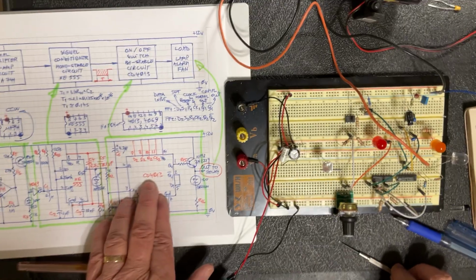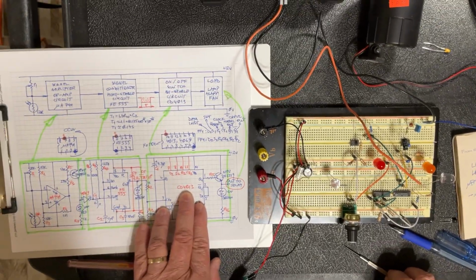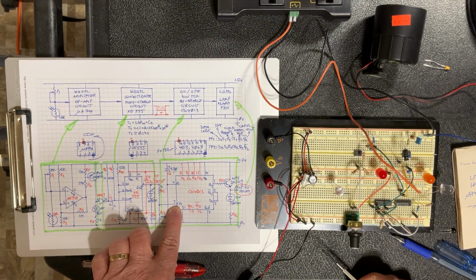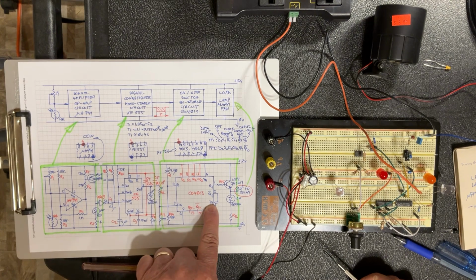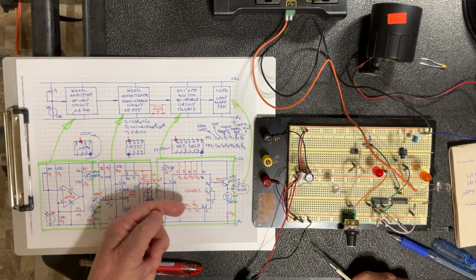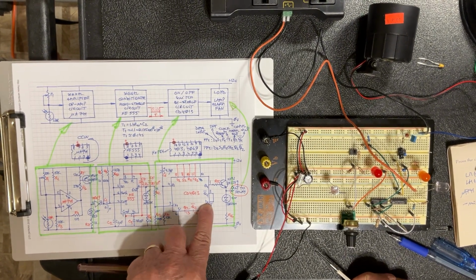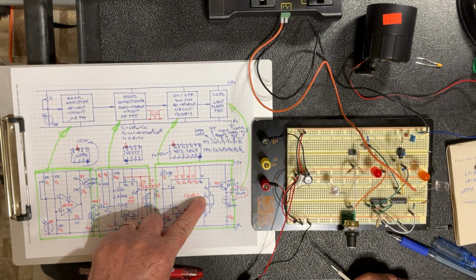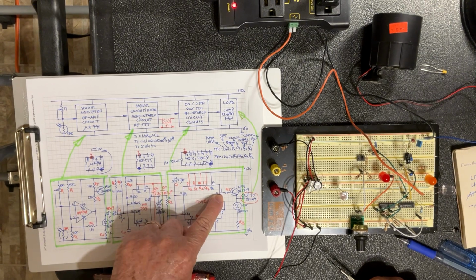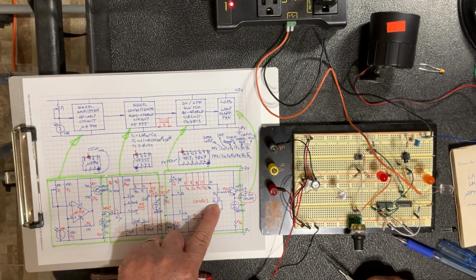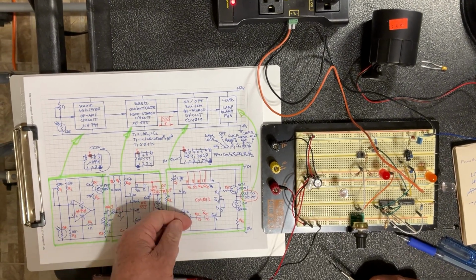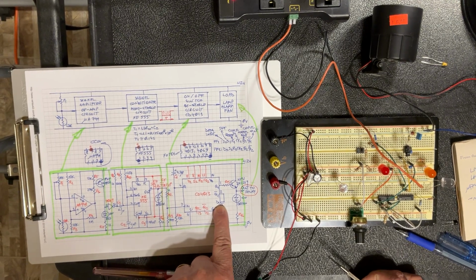Good. So now back to the flip-flop 4013. What happens is, anytime it receives a signal on the clock input, whatever is found on the data input goes to the output. So anytime I press a signal on the clock input, if the data input finds a logic 1 on the complementary output, then it's going to propagate it and the output goes to 1. But when this one goes to 1, the complementary output goes the opposite, it goes to 0. So next time I put a clock input, the data input is going to be 0 instead of 1.